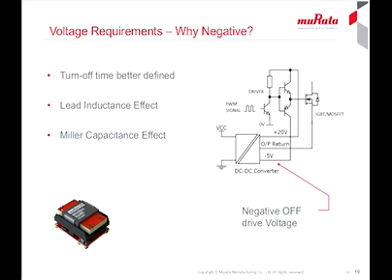If the DC-DC converter were to be rated to give this continuously, it would be very large. So external capacitors on the power rails are used to supply the peak currents, while the DC-DC has a much lower average current rating to recharge the capacitors over each switching cycle. The capacitors have to be chosen carefully to have the right rating for ESR as well as capacitance to avoid stress. If they are too low in value, some of the peak current is sourced by the DC-DC converter, which could cause excessive ripple and overheating.